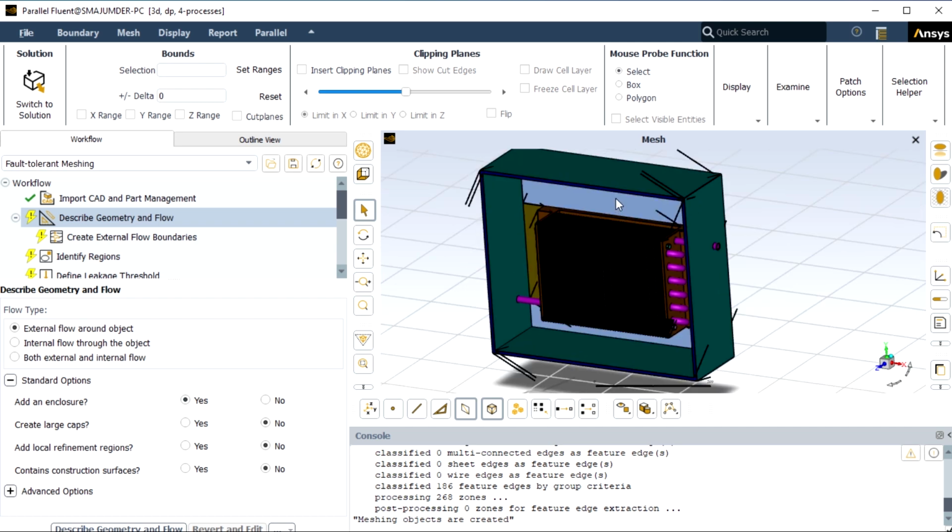We have provided some kind of casing to have a specific amount of air inside this domain. We are considering this one as an internal analysis. That could be considered as an external analysis also. So with some specific setup, we are considering this one as an internal analysis. So here in this case, at this location, we need to define what type of analysis it is. Basically, it is an external analysis, but we are converting this one to an internal analysis with some specific setup.